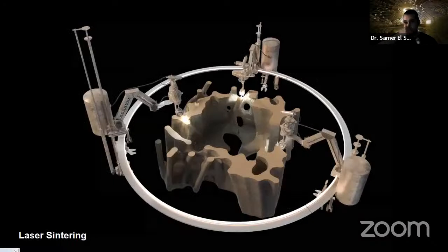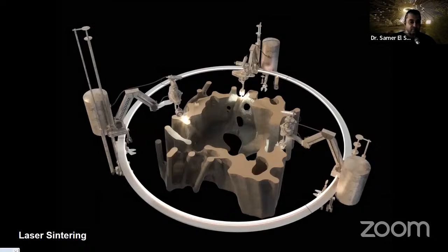ISRU, or in situ resource utilization, is in summary using the local materials, but in 3D printing, we cannot use the same 3D printing methods applied on Earth. Most of the 3D printing methods applied on Earth use water as the main base for the concrete. On the Moon or on Mars or on any kind of new habitat, water is a very precious commodity that we cannot waste on construction. So we have to use totally different techniques.